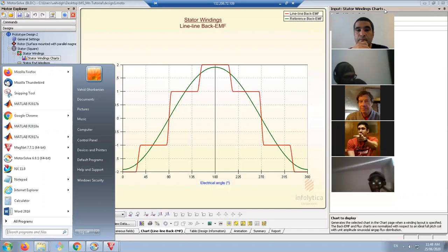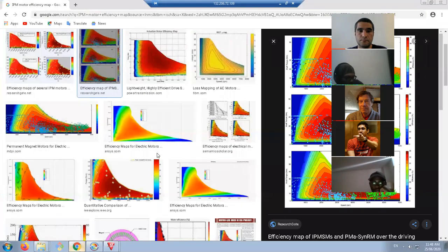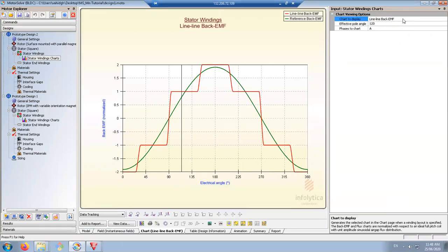I think what you're talking about there is what we call co-simulation, and you can co-simulate with Simulink and MotorSolve, or certainly with Magnet. So the two run in parallel. So Simulink, when it needs information, asks the Magnet model for the data. So that will work. There's also a variant on this where you can export a response model of the motor to Simulink, and that just becomes a block in the Simulink circuit. So there's two ways of dealing with that within the system.